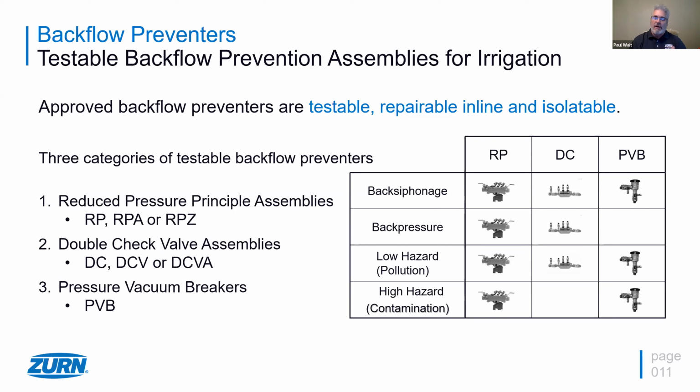And that means, are you putting chemicals in your landscape, whether it's pesticides, herbicides, or just general fertilizers? Would you consider those chemicals a health hazard? And you have to say, yes, if I ingest that stuff, that's probably true. They are a health hazard. So irrigation should be considered somewhat of a high hazard application.